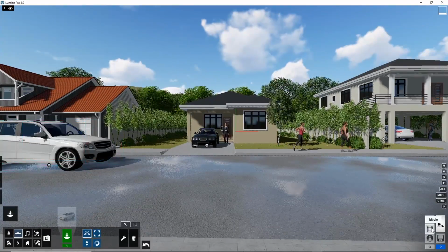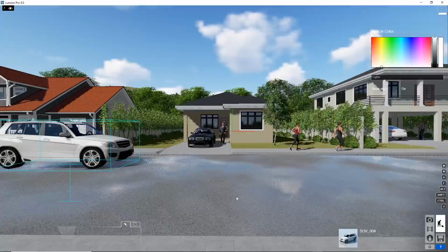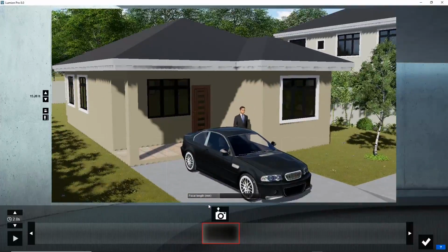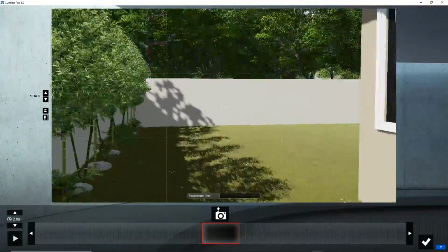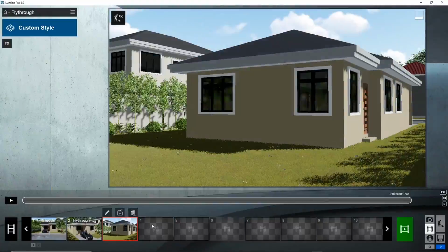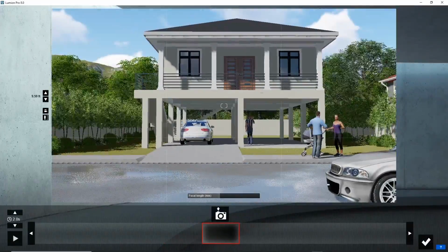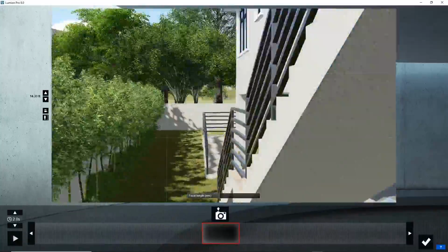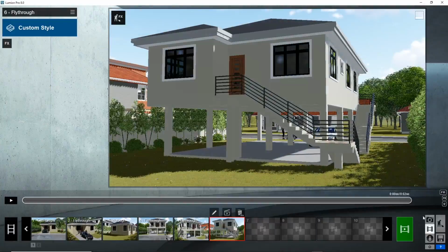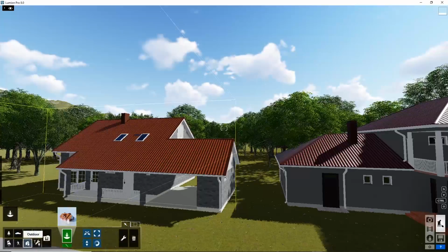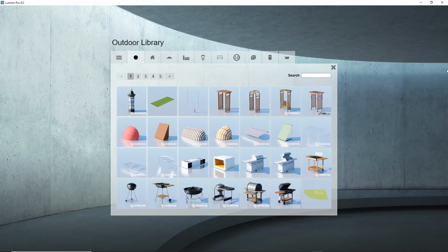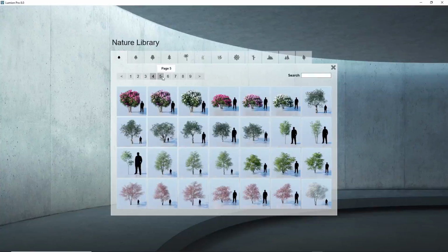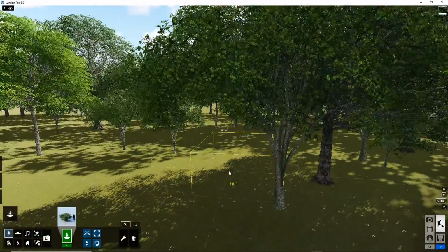And here we are doing the camera adjustment. So the first thing I do when creating a new camera is set the focal distance at 35mm, and from there I just move it around to where I want the shot, and then go in and start editing each individual camera to get the look that I want. So I'd start with one of the basic templates that Lumion has, and then start editing it from there to get the different skies and time of day and everything.